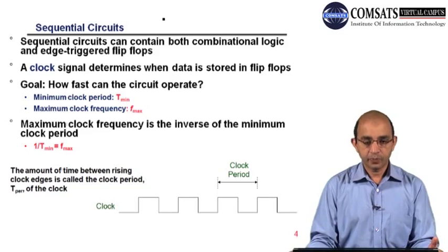If we have a positive edge triggered flip-flop, on the arrival of the positive edge the flip-flop will function by looking at the input. If we have a negative edge triggered flip-flop, on the arrival of the negative edge the flip-flop will behave accordingly by looking at the input which is applied.